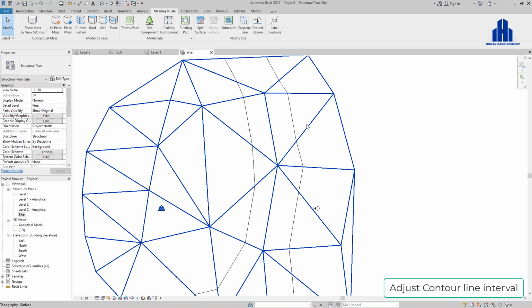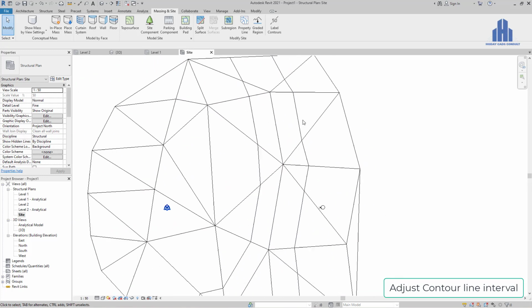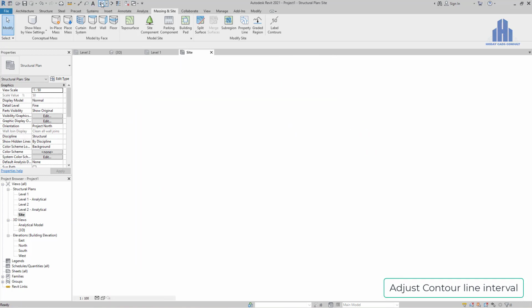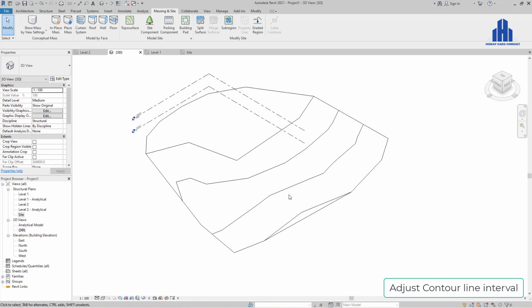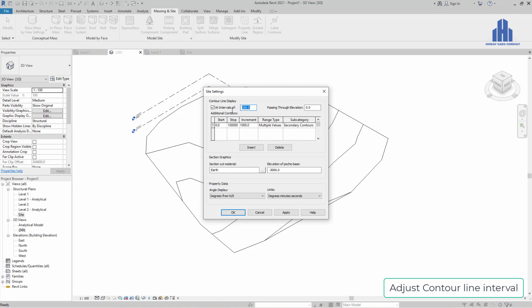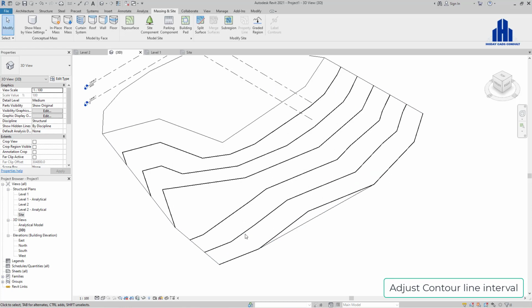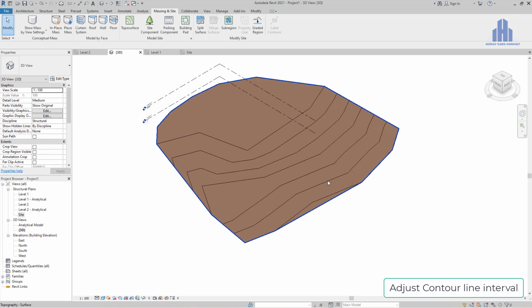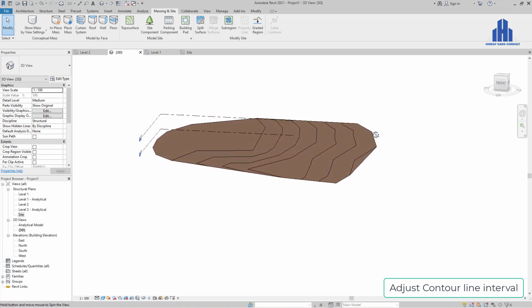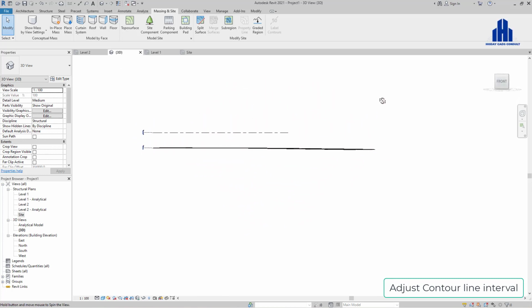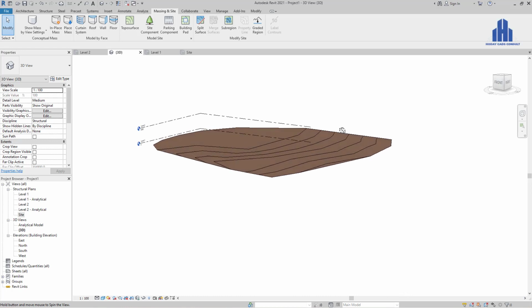So that's broken it into 100. So right here we can see our topo is ready. Let me see, I want to further make it smaller. So this is 50. So I can come here and change this to shaded, so you can easily see how the topo looks.